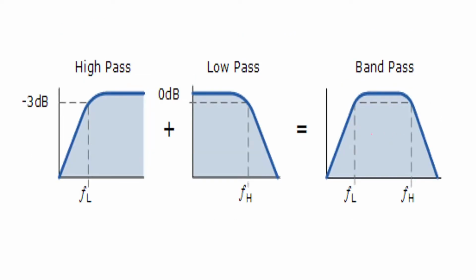Again, in terms of a graph, if you have a graph of frequency versus gain, here you can see the graph. This is your y-axis, shown as gain, and this is your frequency. Here you have high pass filtering. From the maximum gain you come down to minus 3 decibels. That is the half power point, where you get the cutoff frequency FL. This will be your pass band and this will be your stop band.